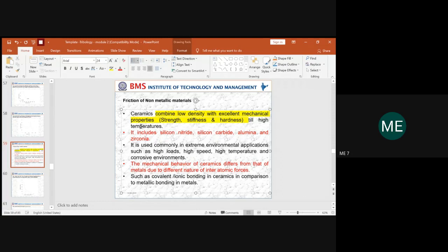Even in annealing and heat treatment, we use a capsule made of ceramics to place the material and heat it. Why? It has the capacity to withstand high temperatures of more than 1800 degrees Celsius, right? As a result, we always go with non-metals, such as ceramics, where extreme environmental condition is an important factor for that particular application.